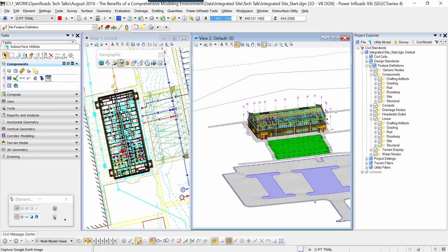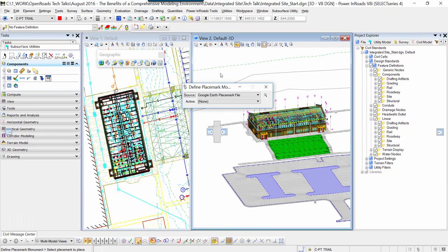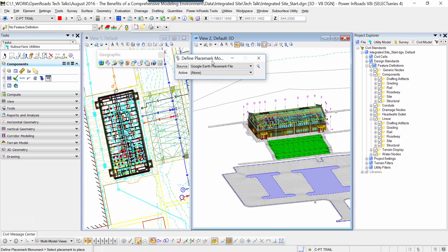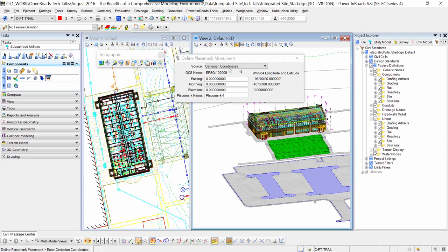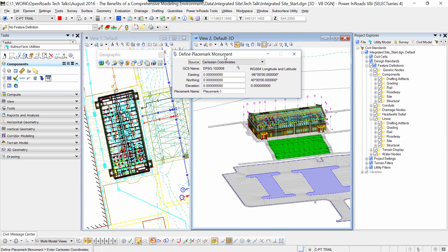In addition to that, in these geographic coordinate tools, you can go into the building model itself, and this can happen on the building designer side of things, and define a known coordinate value for a building corner, or all 4 building corners, or 2 building corners for that matter. So you have the ability to coordinate your state plane building corners with the actual building model.